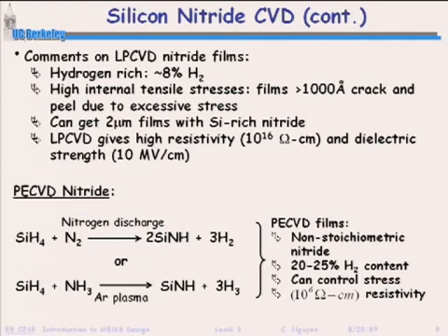We'll go through that later in the course in much more detail. With silicon-rich nitride, though, you can get 2-micron thick films without big problems. It can be a very low stress material. You can make suspended structures that, if designed correctly, do not buckle and are not bending in and out of the plane of the wafer.